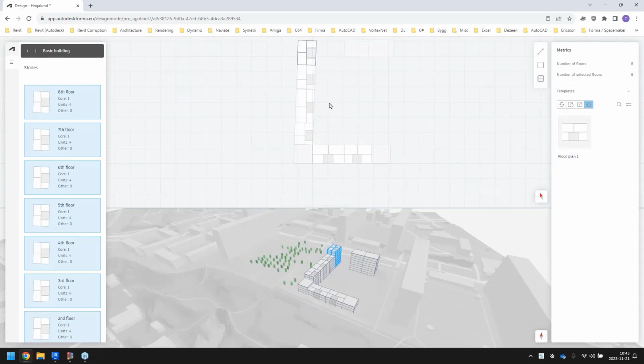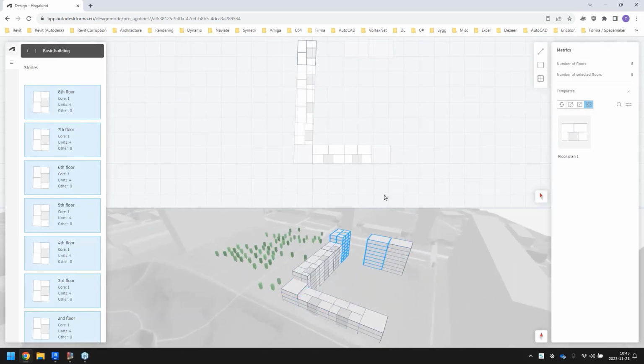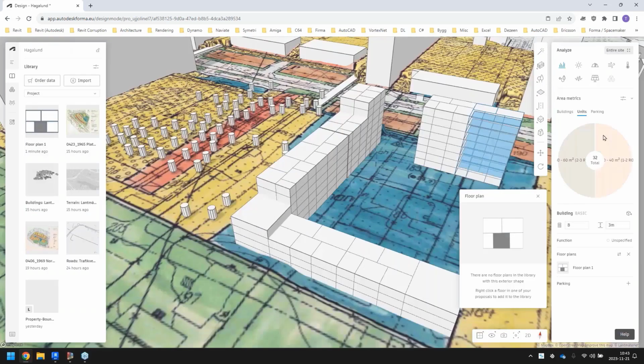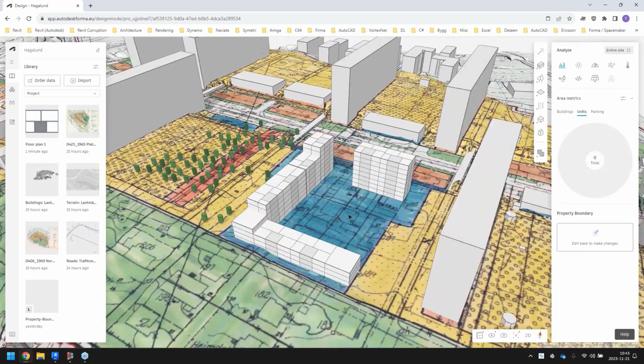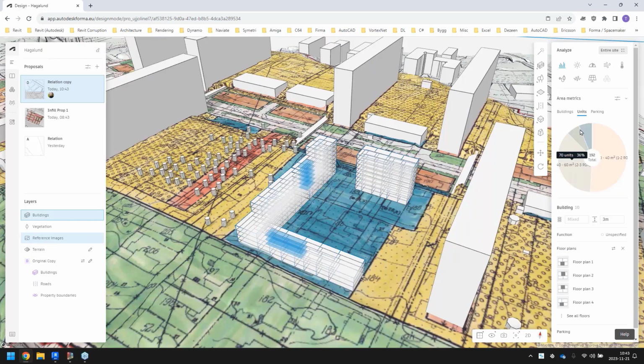And just by doing this, I have created units on each and every one. So each and every one except the corner building here and these ones. Oh yeah, we should do those. So double click that one. There, go units on that one, double click that one, and do units on that one. Go back, and now I know I have 32 floors. If I select all of my buildings, there, I have 192 apartments.